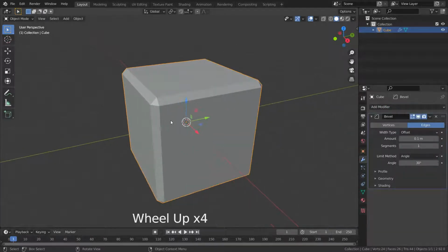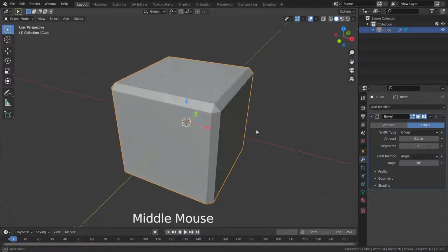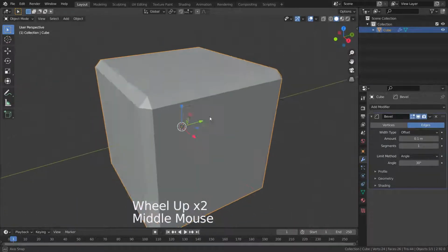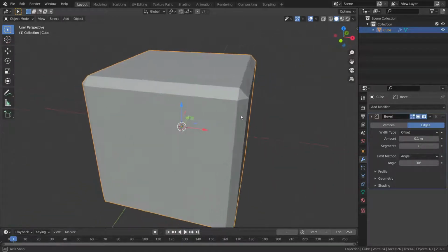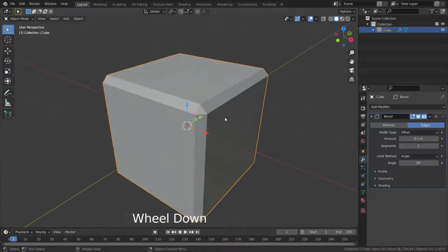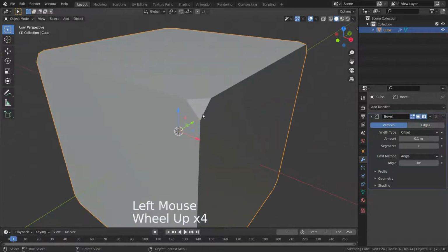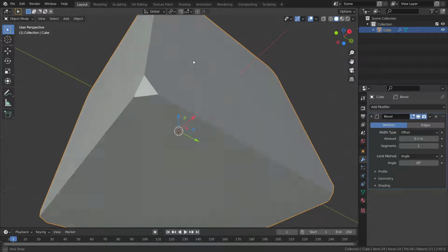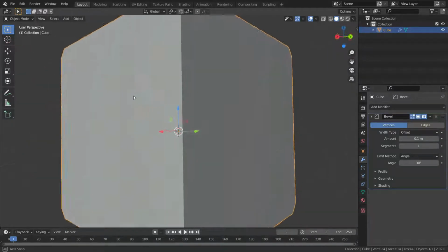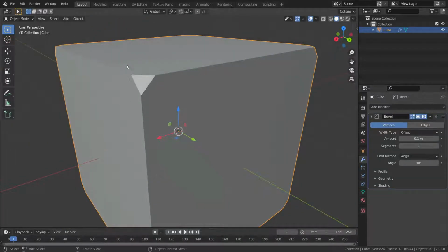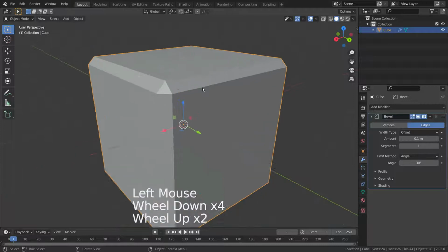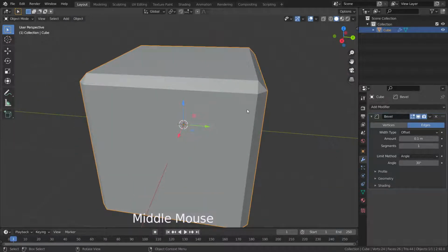The Bevel Modifier bevels the edges or vertices of the mesh it is applied to, with some control of how and where the bevel is applied to the mesh. We have two choices here to bevel: vertices and edges. If we select the vertices, only the areas near vertices are beveled, the edges remain unchanged. If we select edges, it bevels the edges, creating intersections at vertices.